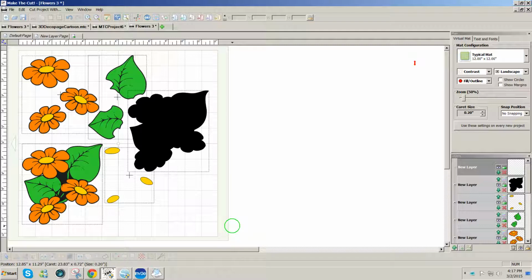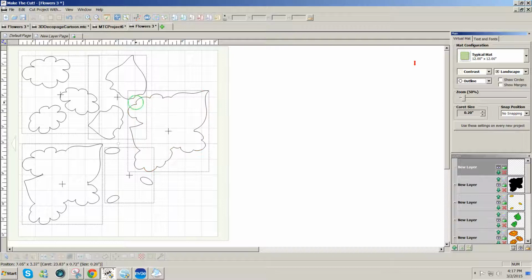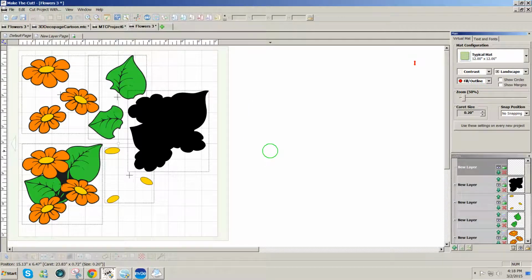This episode we're going to talk about how to get your new design that you created and make the cut exported so that it'll work in other software. Because these designs have textures in them, exporting as SVG is not a good option. So what we like to do, if we want to include just the texture lines that we created, if you recall, if you go to outline and you see that we've just got the outlines here, and these outlines are filled with pictures, but SVG files do not hold the pictures. So there are a couple different methods that we use to get these files into other software efficiently. So I will show you a few of those options.